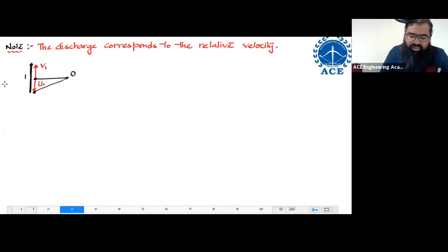Now, this much length over here corresponds to which velocity? It corresponds to VR1 velocity. Please understand this thing. As the fluid is going up, nozzle is going down, entire length from here to here is going to be filled with the fluid. The corresponding velocity is VR1, and the discharge over here should correspond to this velocity. Therefore, the value of discharge should be corresponding to relative velocity only over here.